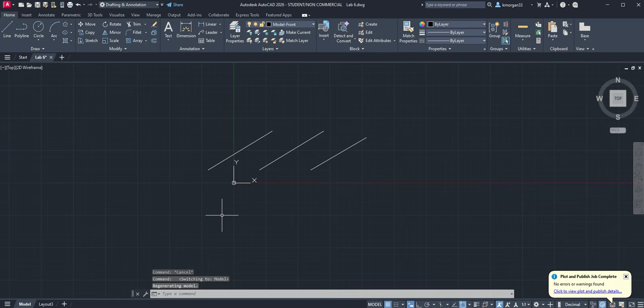Yeah, so now you know what is the absolute Cartesian coordinate, and then relative Cartesian. Now you know the polar coordinate, how to play with the angles, how to enter. So for absolute and relative, we do pound and then at mark. Of course, for polar, we have to put the third one, which is your angle. So we jump by typing comma. Of course, for the angle, you do the angle sign.